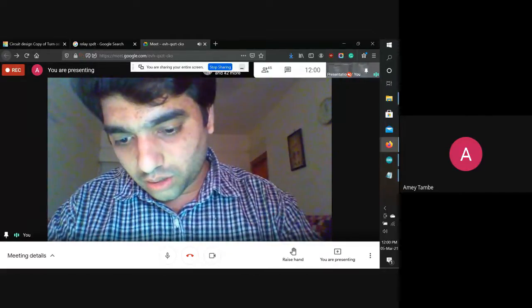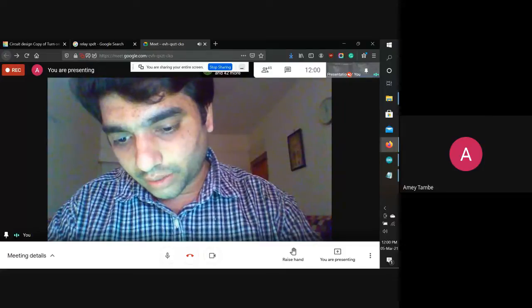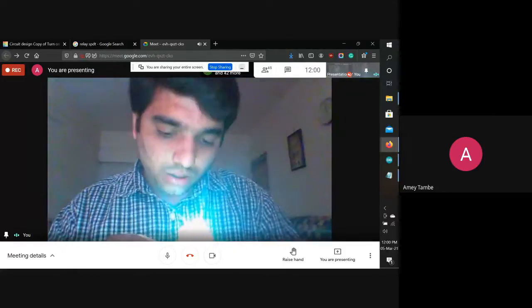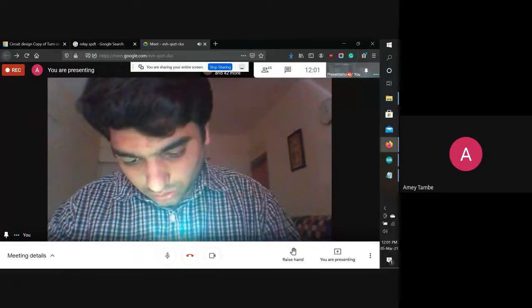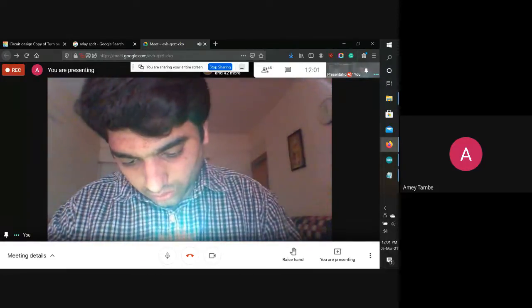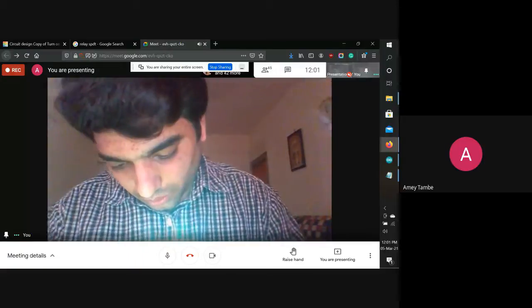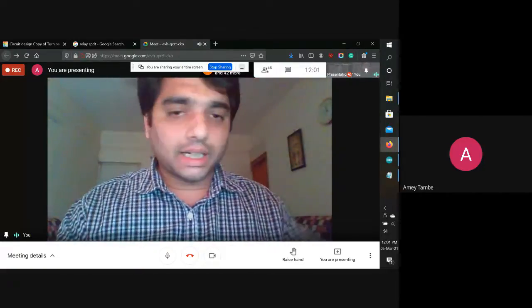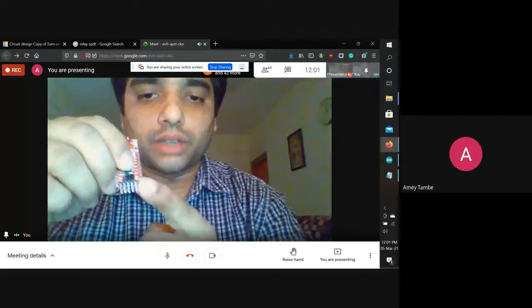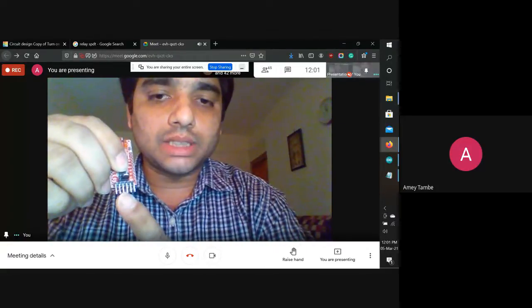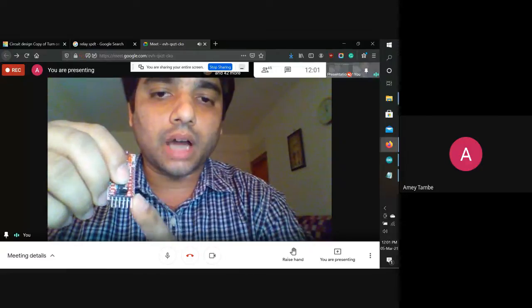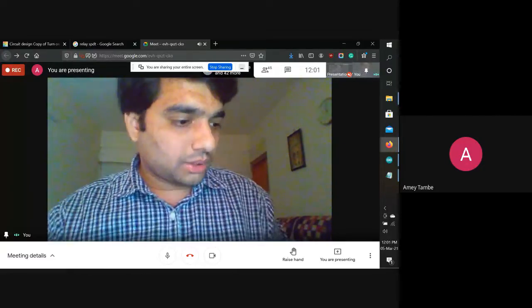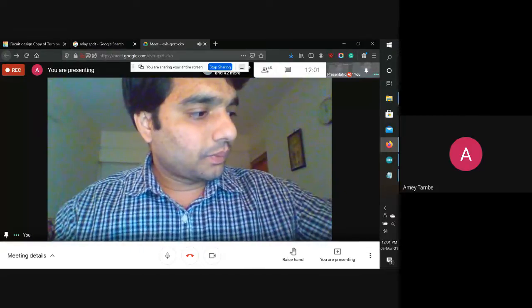One is DTR, then RX, TX, then VCC, then we have ground. So we'll require exactly four pins out of this: one is ground, one is VCC, and the others are RX and TX. That will be going to this one. So let's interface this.